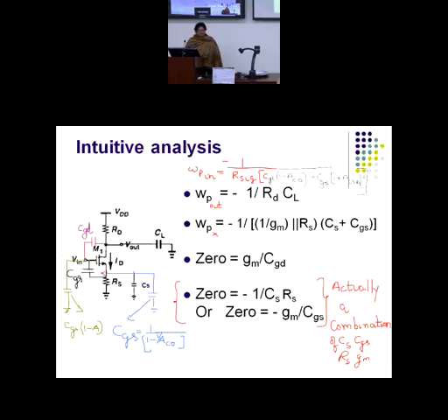Yes. So this is one case where we are saying that the CGS path is becoming active earlier than the CS path. Now what may happen is the other way around. Suppose your CS path becomes active earlier than CGS. That means CS is more than CGS. Then your 0 will become... what will be your 0? Anybody who has done it?